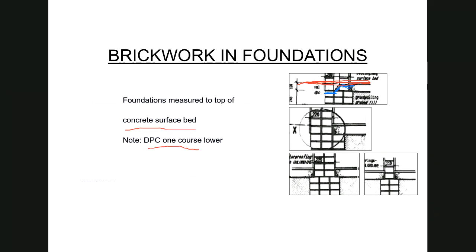So this complication of where the DPC is and what our cutoff line is, we need to now factor into our foundation brickwork measure. So also for detail 2, where we don't have the implication of the DPC, our cutoff point is over there. Similarly, in detail 3, our cutoff point is over there. And for detail 4, our cutoff point is over there. But now in every one of the details that I have shown you, we have a little bit of a complication.